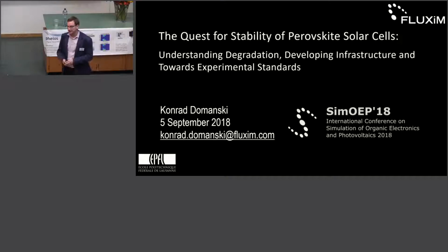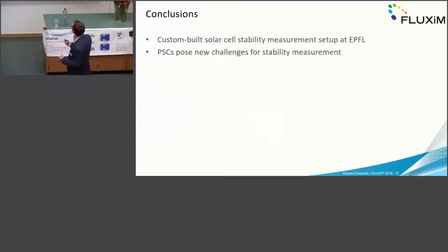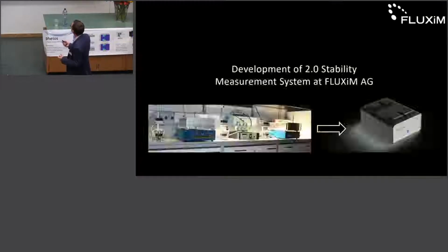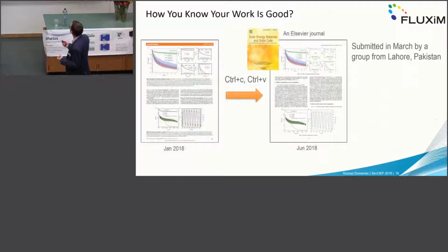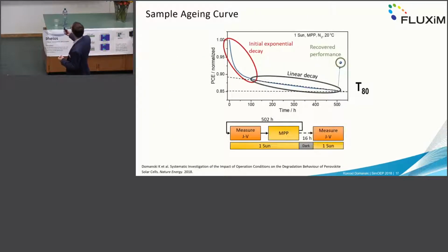I mean, you still have the linear component of degradation, which is much slower, but nevertheless, still pretty bad. If you look at this curve, yes, most of the degradation is reversible on this timescale, but there is also this component. And I think if you translated this linear degradation, assuming that it's fully linear with illumination time and intensity, and assuming 4 hours of daylight a day, you would arrive at somewhere between 2 and 3 years. But of course, things are improving, and I'm convinced that eventually we'll crack it. But there is still a way to go.